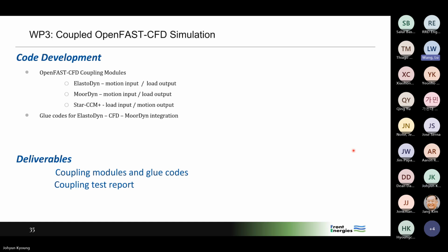We also observed in some of our research very high sensitivity of the tuned hydrodynamic coefficients, such as drag coefficients, to different platform geometries and sea states. This sensitivity poses further challenges to model calibration. So in this respect, high-fidelity CFD simulations have an important role to play in providing reliable reference floater response under realistic conditions for the tuning and validation of mid-fidelity hydro models.